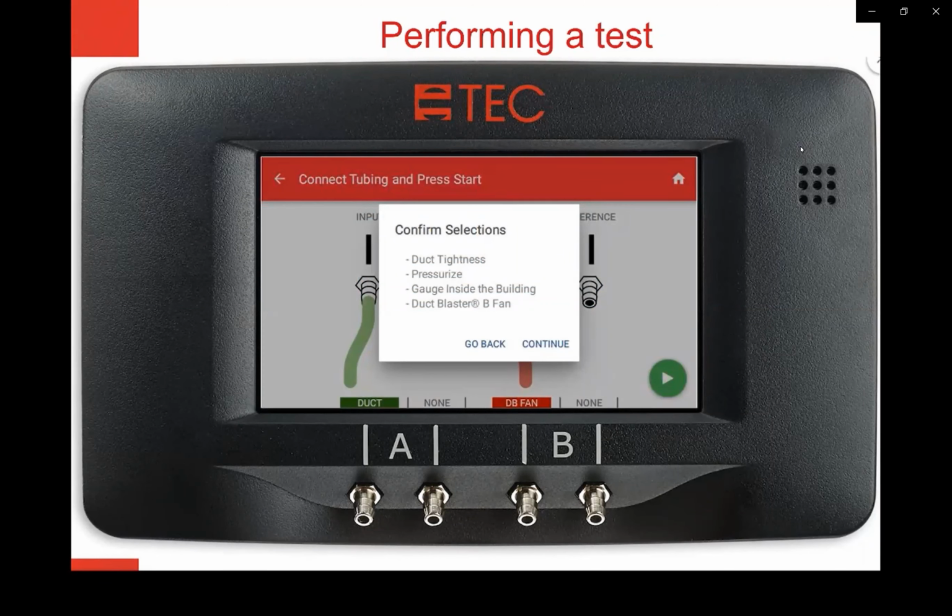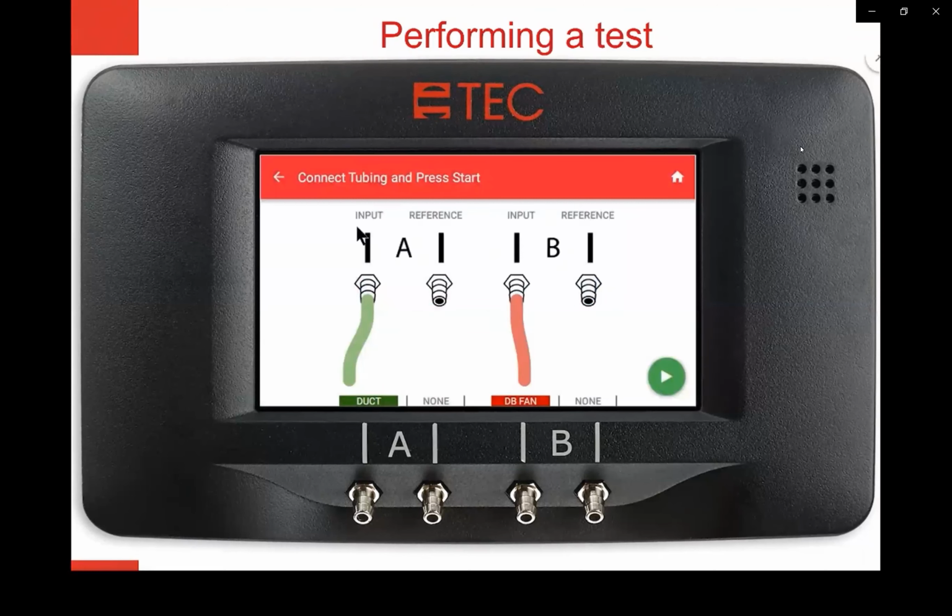Now it's asking us to confirm our selections. We've chosen duct tightness, pressurized, ducts inside the building, and we're using the duct blaster B fan. So hit continue. Now it's showing us that we want to connect the tube from the input on A going to the duct, and input on B going to the duct blaster fan. It shows us how to connect that tubing, and then we'll hit the start button.